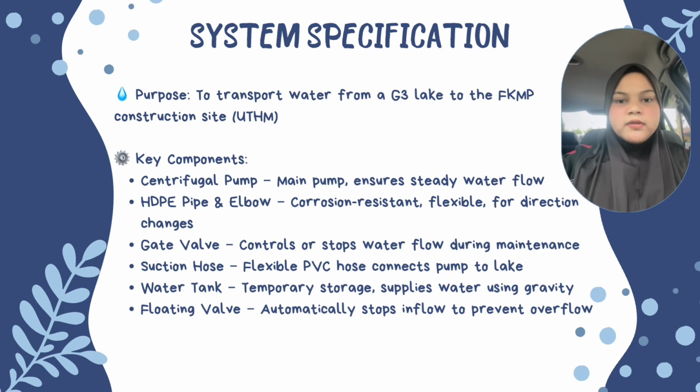The centrifugal pump acts as the main pump, ensuring a steady and continuous flow of water from the lake to the site. HDPE pipe and elbow are used to carry water throughout the system, being corrosion resistant and flexible, making them suitable for directional change and long-term use.